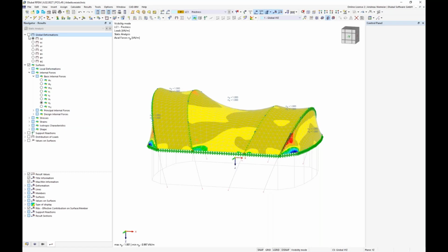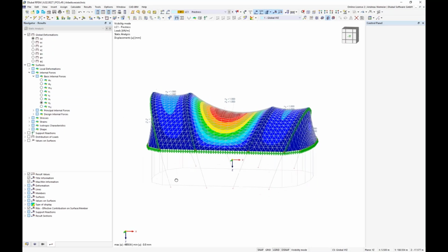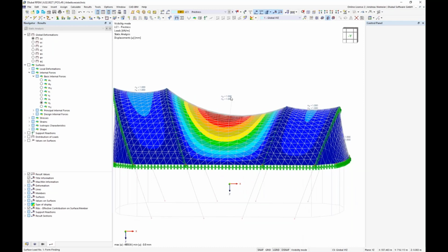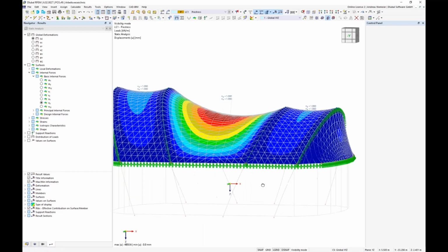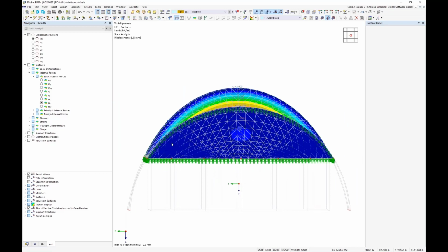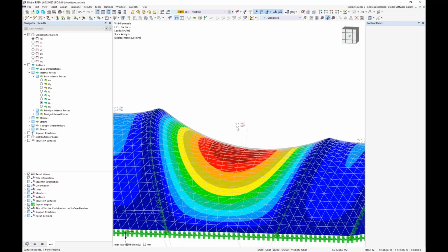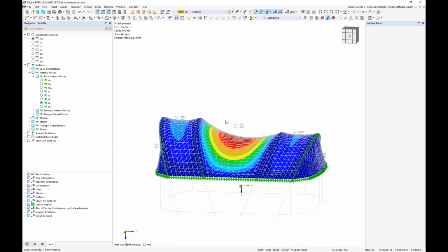But the only unnice thing is that we have here a really big sag, and I want to lift it a little bit so that we don't have such a big sag. And to reduce this sag, we have to, let's say, reduce this tangential pre-stress direction. For this, we should change one figure here, but I don't know what is y and x at the moment. We have to specify it.